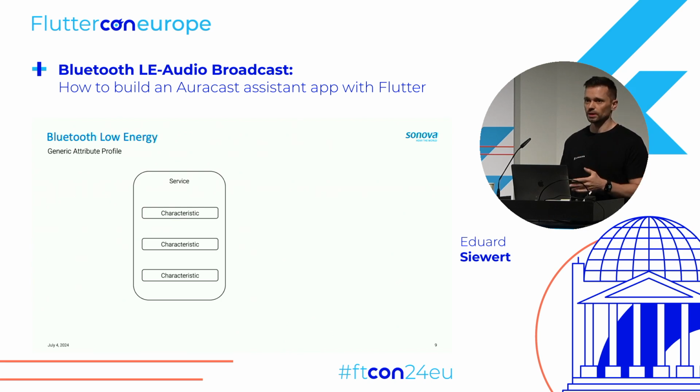This is more for use cases like wearables or sensors, which have limited power resources. And there you only want to read maybe a value every second or a couple of times per second. And for the rest of the time, the actual Bluetooth radio can be in sleep mode on these devices to save power. And this is exactly what we are using